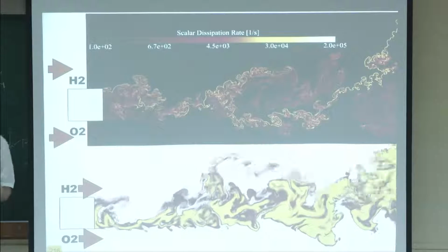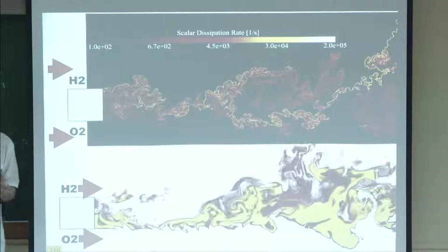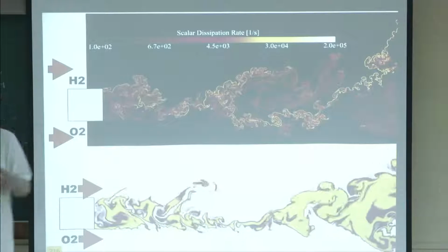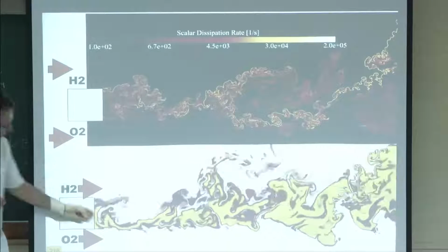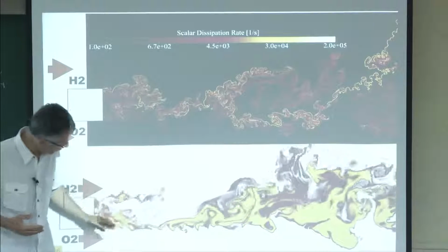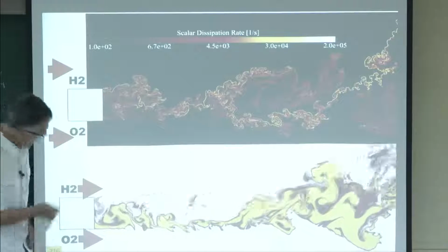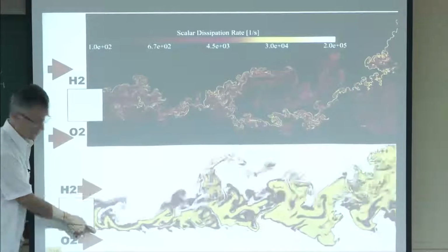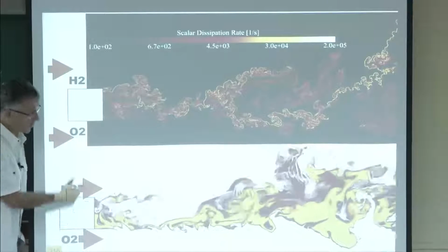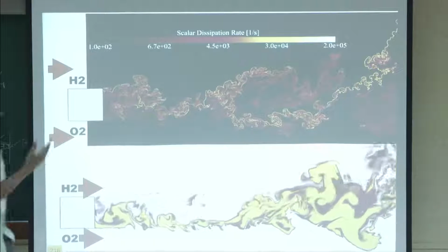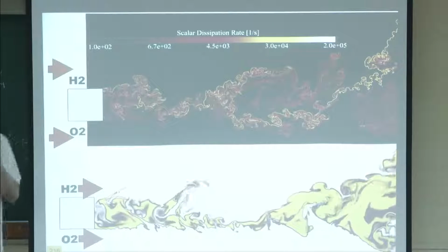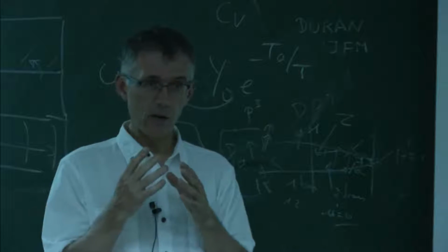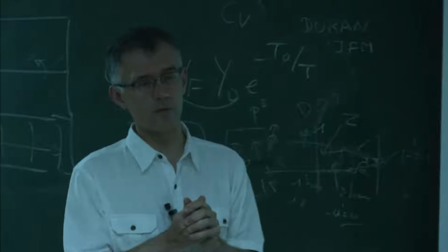This is the same flow, now with full chemistry, so it's 10 species for H2, 19 reactions. And you can see that it's saying the same thing that we were saying before: chemistry is fast enough so that the flame is always stabilized here between the lips. Between that point and that point, there's 0.5 millimeter and 200 points for the resolution. So we cannot even do it in 3D. That really tells you that in a case like this, you can simplify your CFD task a lot by simply recognizing that chemistry was not the problem.